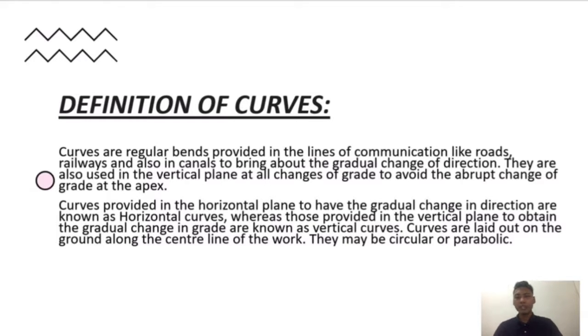Curves provided in the horizontal plane to have a gradual change in direction are known as horizontal curves, whereas those provided in the vertical plane to obtain a gradual change in grade are known as vertical curves. Curves are laid out on the ground along the center line of the work. They may be circular or parabolic.